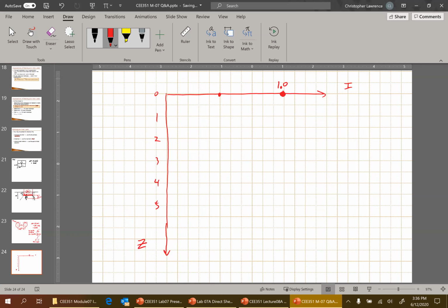So it is the depth related to whatever's the width of the load. If it's a really wide load, then the influence goes deeper. If it's a really narrow load, then the influence is not as deep. But it's the same relationship either way.